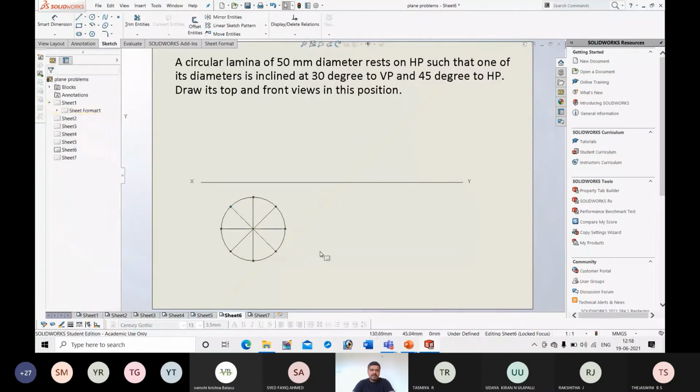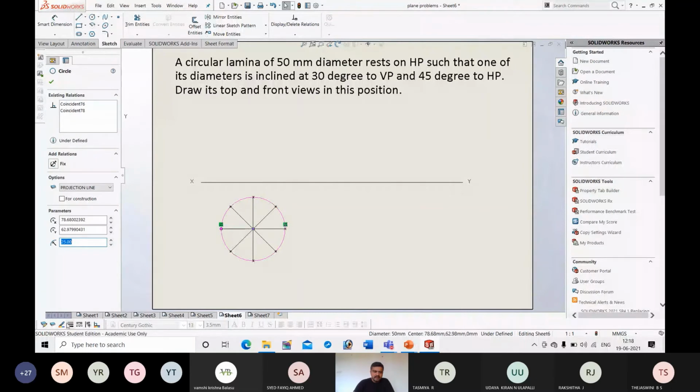So first divide the circle into 8 equal parts like this. First draw the vertical and horizontal lines. Next, using the protractor, draw 45 degree inclined lines so that you will get these points. Okay. Next, after dividing the circle into 8 equal parts, name them.